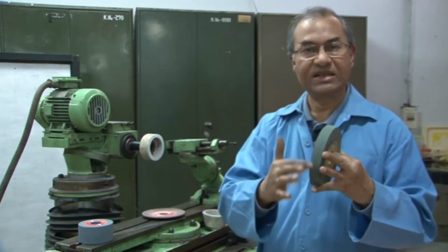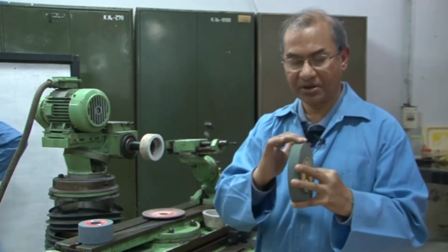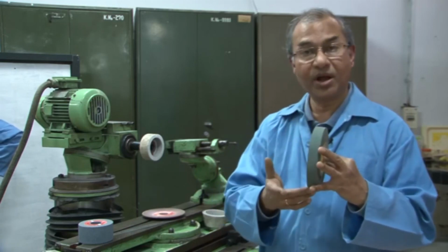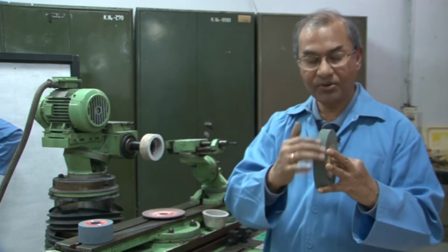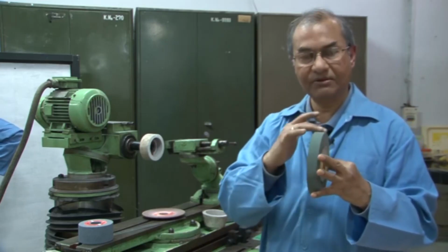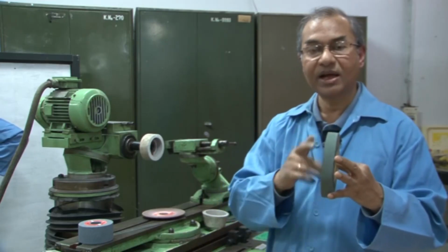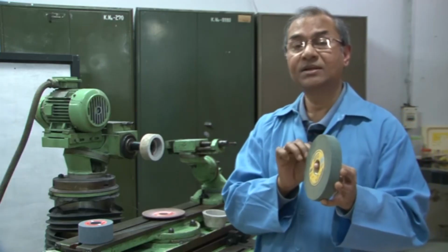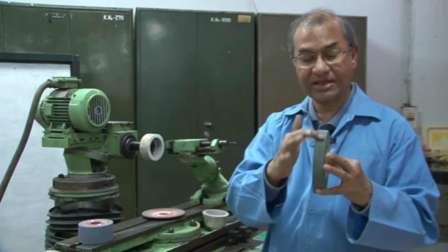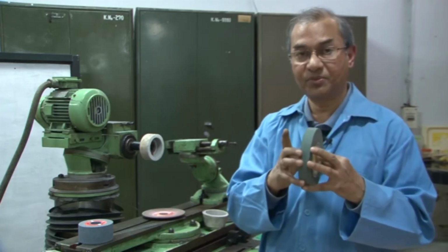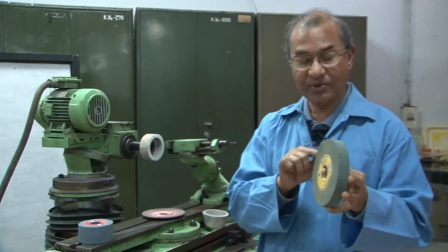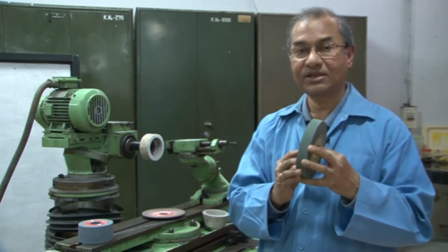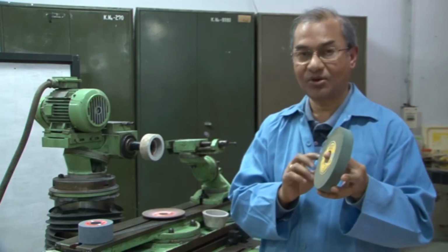So, that is a very negative factor for the grinding process, and in that case it is said that the grinding wheel is glazed, that is called the glazing of the grinding wheel, because those worn out grains which will be on the surface of the grinding wheel, which are not coming out, will look like a glazed surface. So, that is not good. Then those worn out grains, or the glazed layer, have to be removed forcefully, and that removal is done by a diamond pencil, a process called wheel dressing.